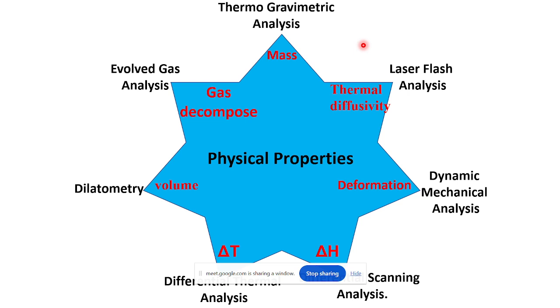Now why is this happening? Because if I am increasing the rate at a higher level, maybe, because we are probing temperature by a thermocouple, the sensitivity of your thermocouple is also very important. It may be possible that that much temperature has not reached the material. If we are increasing the rate very fast, it will sense that temperature when it is already right shifted. That's why we will get 160 or 165, but it will not be very absurd.